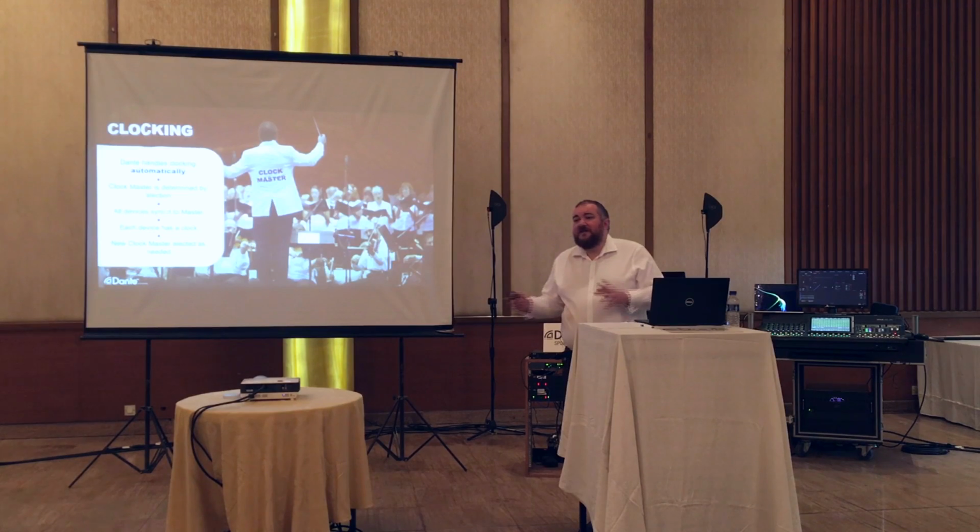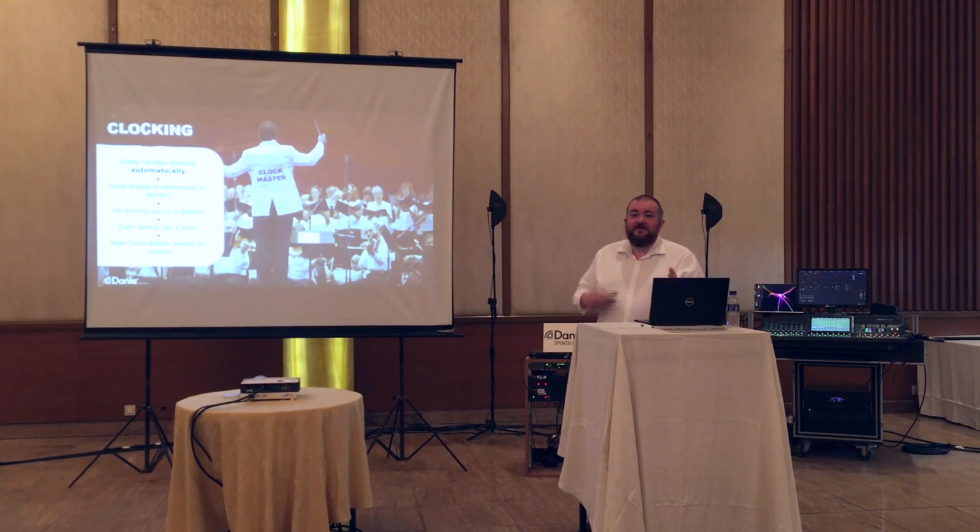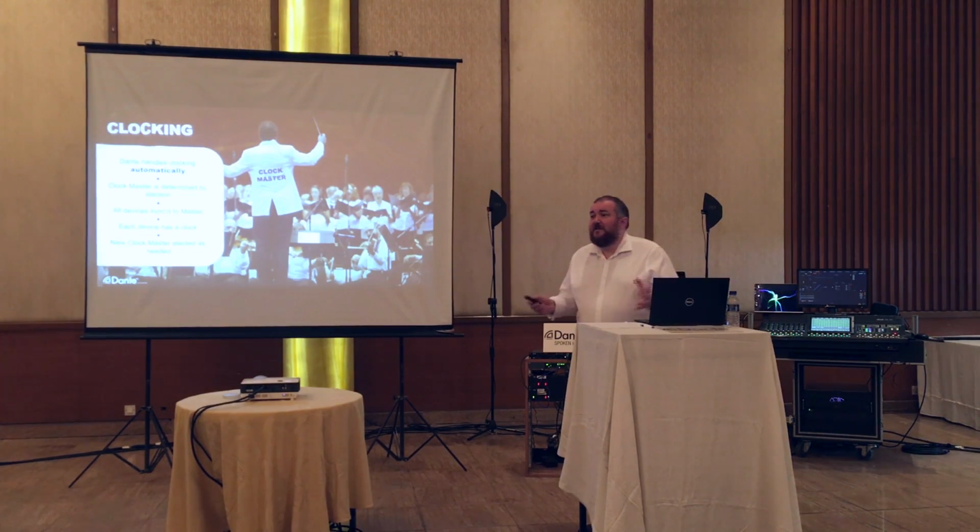I think what's happening, certainly with video and audio together, if you look at the SMPTE standards, SMPTE 2110 for video and SMPTE 2110-30 for audio, both use the SMPTE 2059 standard for synchronization, which is a profile of PTP. So with Dante Domain Manager, we allow synchronization and exchange with SMPTE 2110. So that issue with video sync with audio just goes away. And we can have dynamic clock mastership within the video and the audio systems.